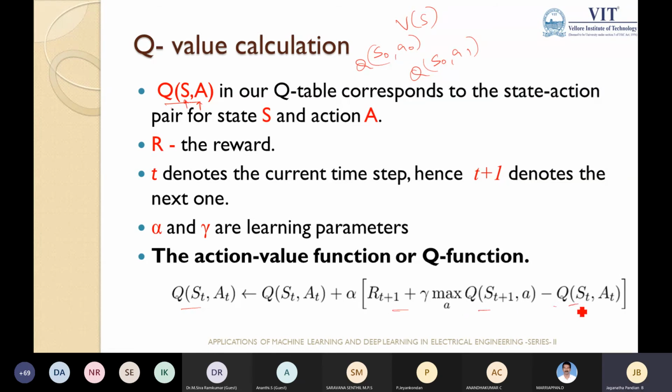Of course, if anybody already has exposure to other algorithms, this is very close to a SARSA-like algorithm. If you have time, you can Google SARSA-based robotic applications. The main difference is this maximum term will not be there in the SARSA algorithm. In Q learning, you will have this max. It's talking about the maximum, where I have the next step maximum, and based on that, we are going to update. It is not simply taking from the next state, but the best next state.